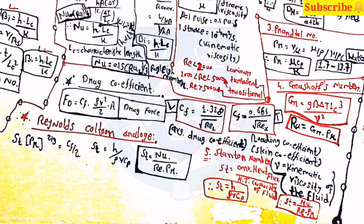Then the fourth one is the Grashof number. Then after that, the Reynolds-Colburn analogy: here St is equal to Nu upon Re into Pr, where St is the Stanton number, Nu is the Nusselt number, Re is the Reynolds number, and Pr is the Prandtl number.